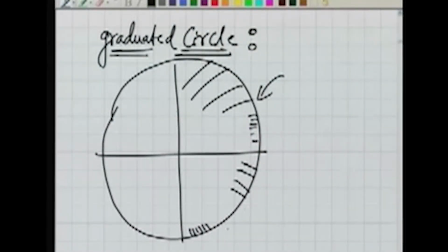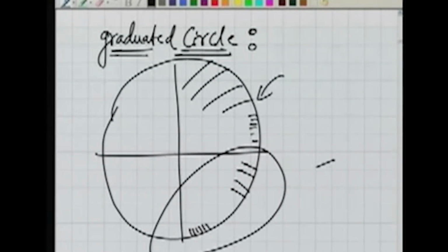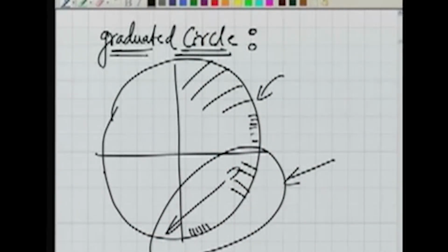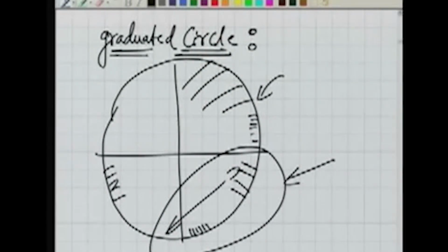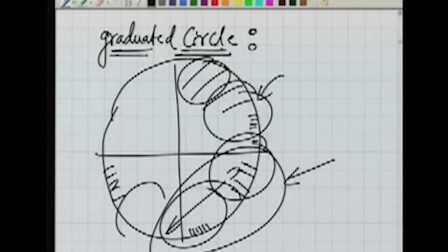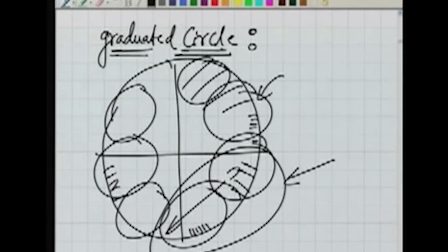Or maybe because of the temperature also, the part of the graduated circle is exposed to the sunlight, so because of the temperature it is expanded while the rest is not. So if this is the problem in the instrument, how to eliminate it? We have seen the answer of that. The answer was we should take the observations in different parts of the graduated circle, and the mean of these. This is so in the method of repetition.